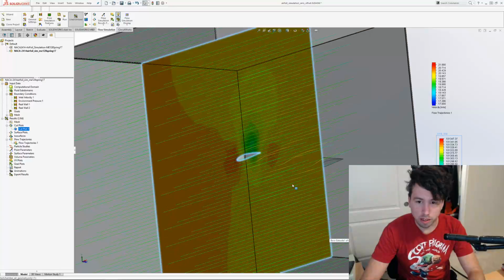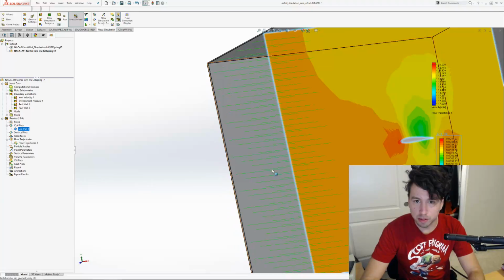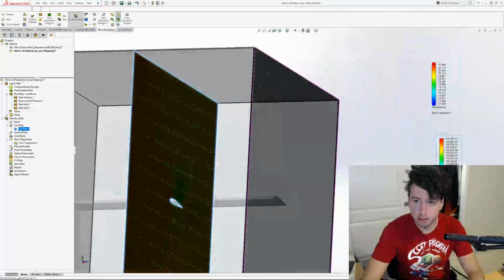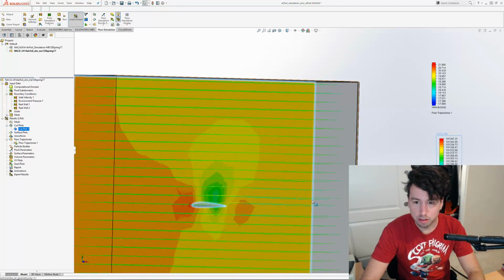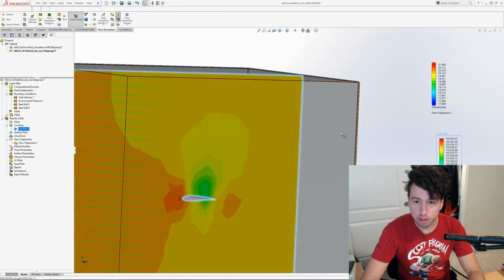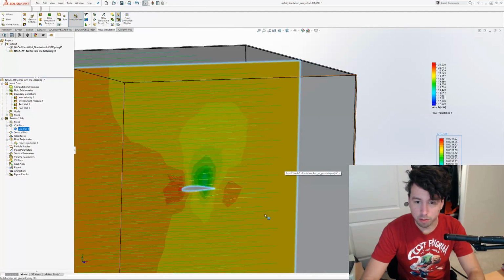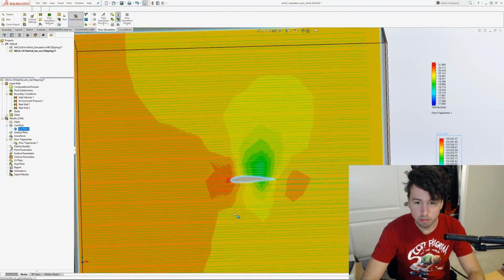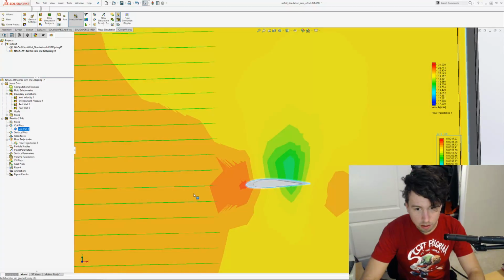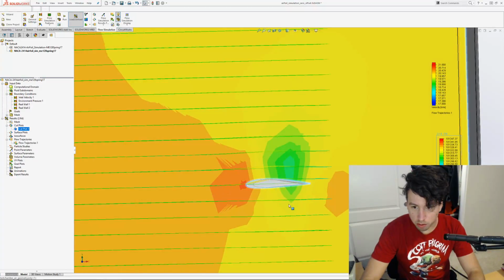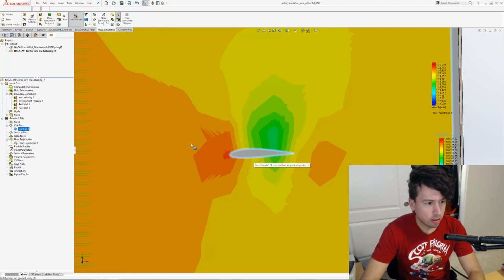I'll show you the finished result right now. I have a pressure contour for a 19 meter per second flow inlet condition. Walls are just real, no roughness, and the outlet is to atmospheric. And then I have flow trajectories for the fluid velocity, which you can see interact right here, and then flow above and below. And we can mess with the settings. I'll explain more to that as we do this.